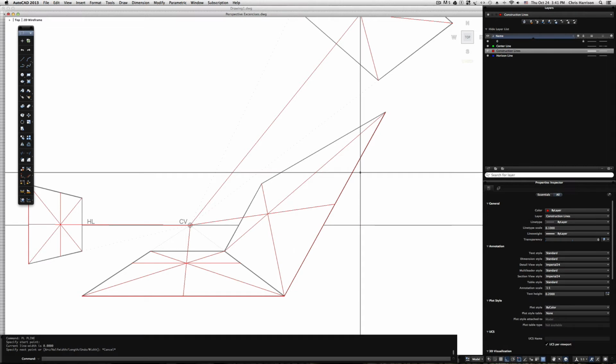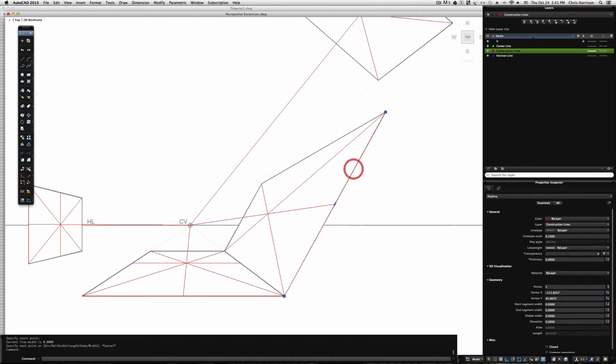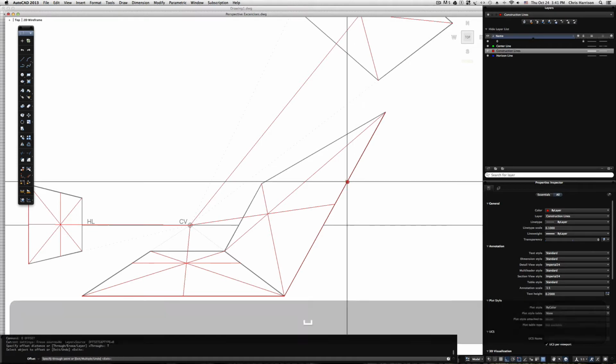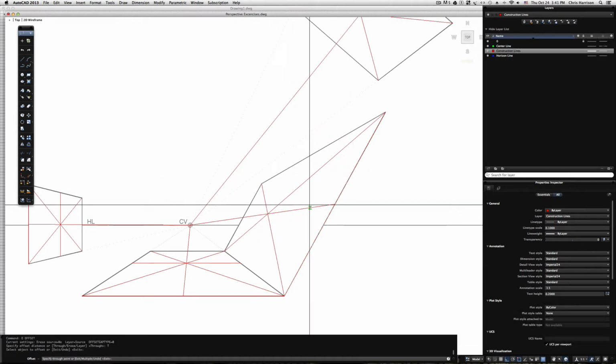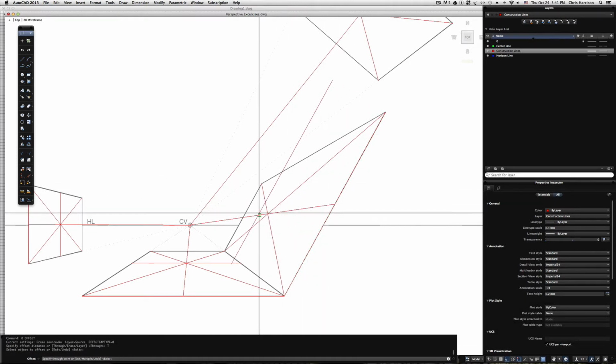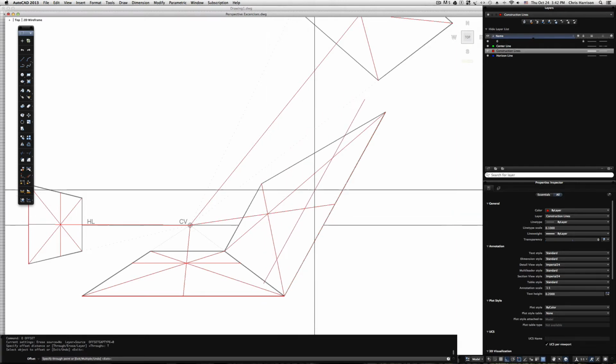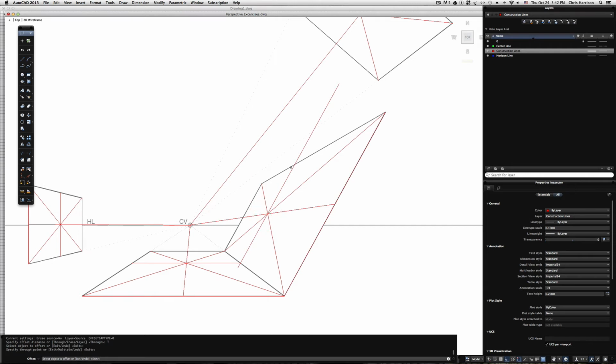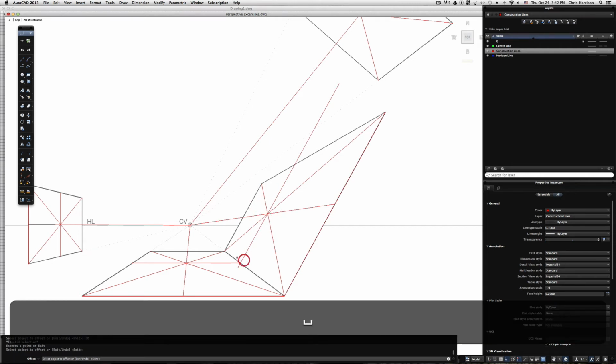And this guy, really this becomes an offset. So it's not just a straight line. I'm actually going to use my offset tool in AutoCAD. You could use a roller ruler, which would really be helpful in this exercise doing it by hand, but make sure you're parallel with this line and just bring it straight over to your geometric center. And it should coincide with the center that we drew previously.